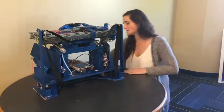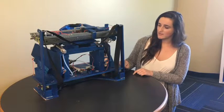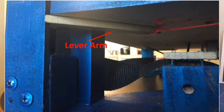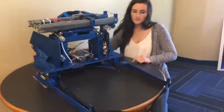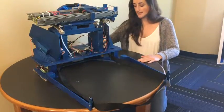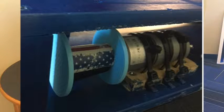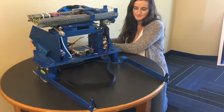What happens is a solenoid back here pulls back, and a weight is resting on top of it that's attached to some strings, which connect to lever arms that drop these arms down. So I'll go ahead and show you that. The solenoid dropped, the weight came down, and the straps came out. Then a motor runs back here and winds up the straps and pulls the rocks all the way into the system.